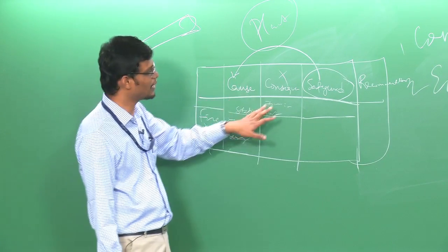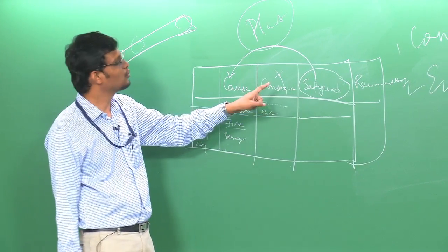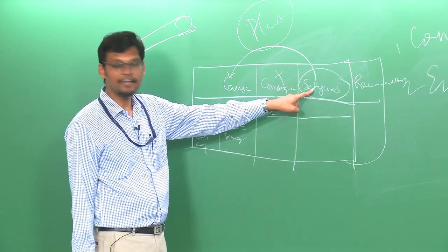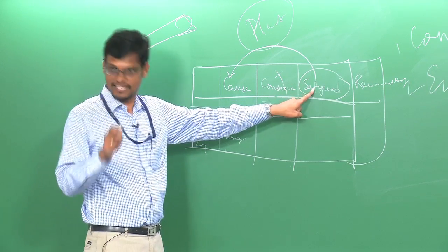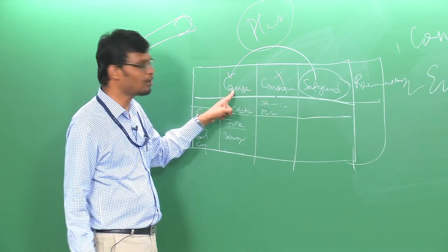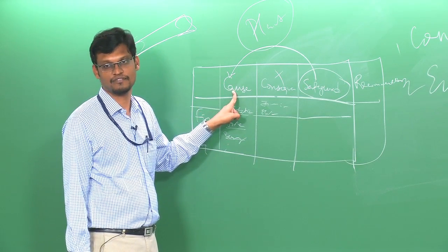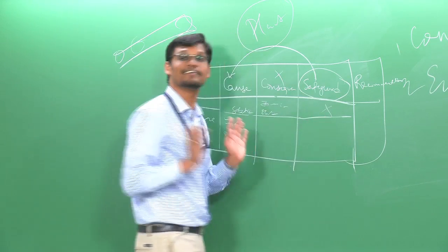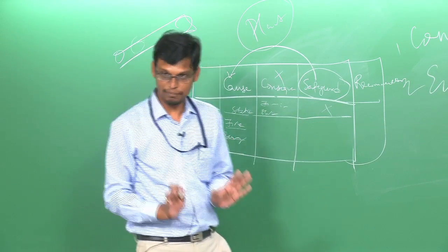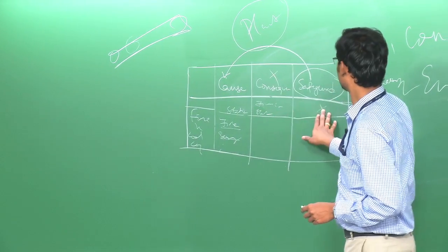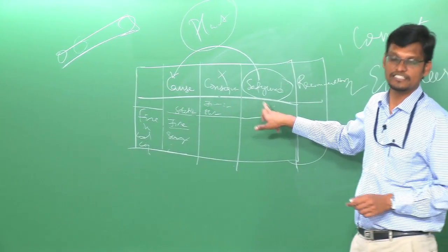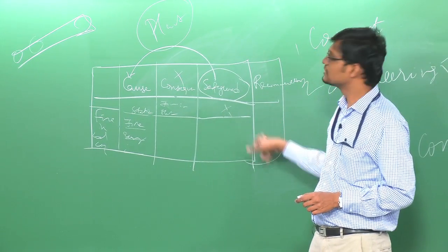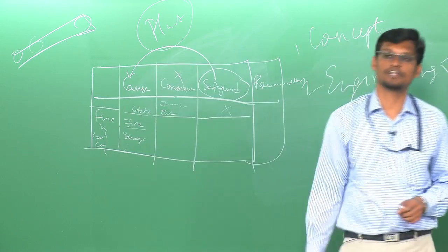See, what generally happens, what people make the mistake of, is you try to mitigate the consequence. No. This safeguard is permitted as a safeguard only when it mitigates your cause. Otherwise, you will give credit to something which is not actually technically permitted. So, this is what you do. You look at the safeguard, if it is not sufficient, you will convert it into a recommendation. So, this is what happens in a what if analysis. Okay.